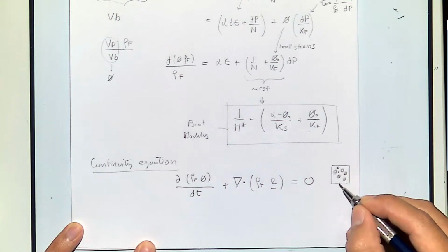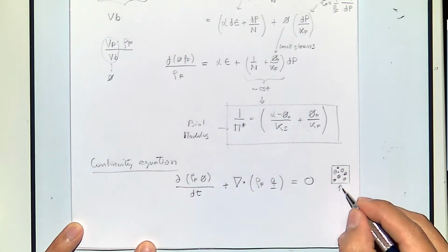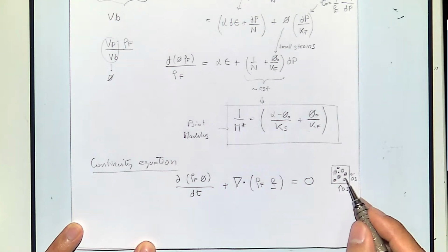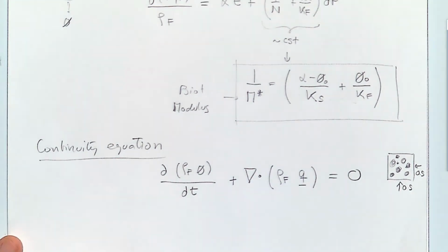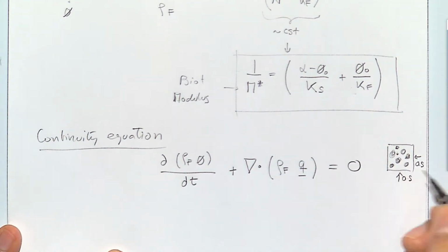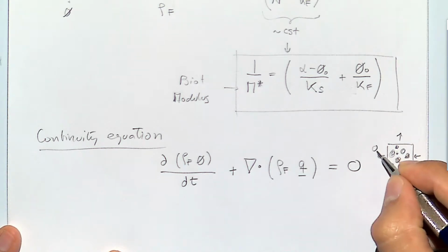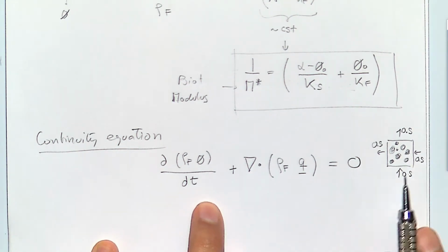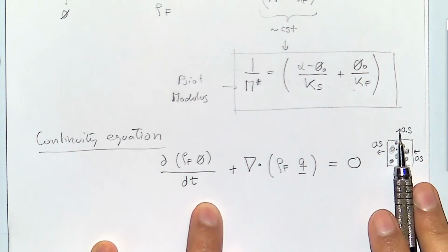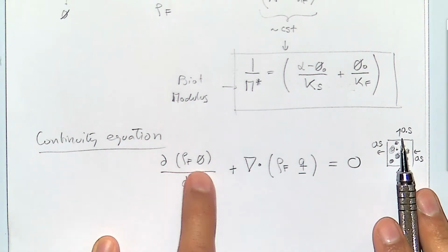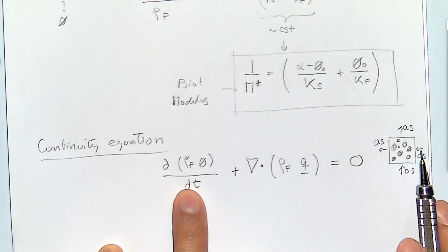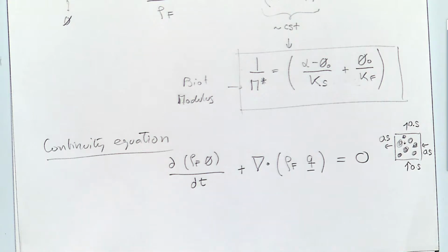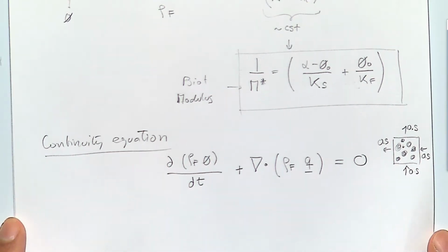The second term would be that, let's say, if I get 0.05 and 0.05 from here, I'm entering a total of 1 into the porous volume. Well, if that's true, then 1 also has to exit. And if this number is different than 1, say if here I have 1 and here I have exiting 0.9, that means that the density inside or the porosity must be changing, one of those. So those two compensate in order to write this diffusivity equation.